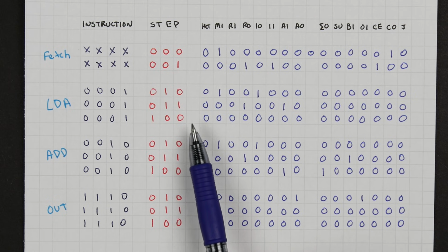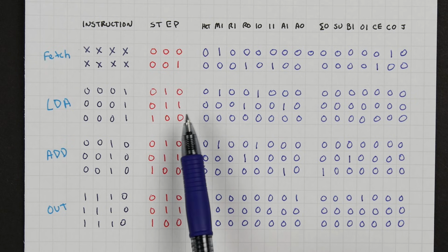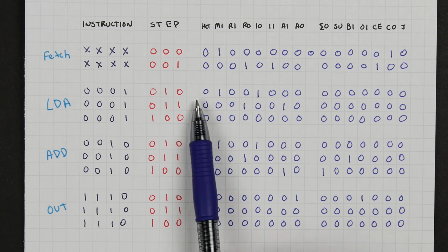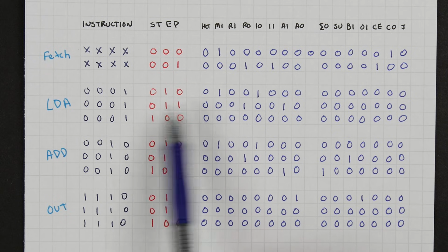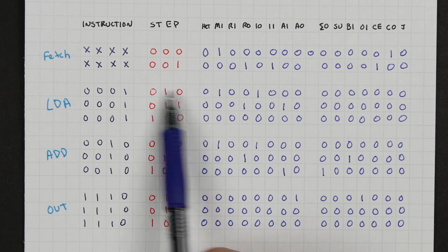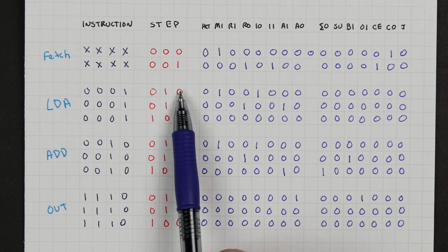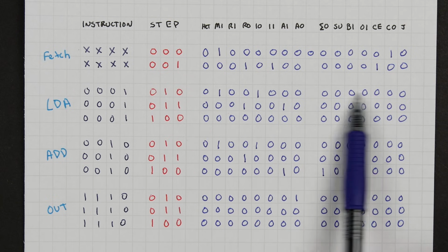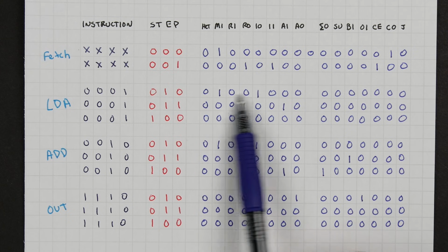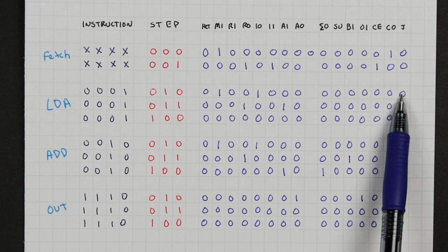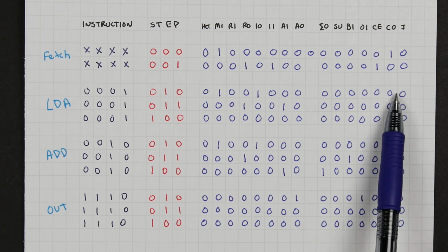But you may also remember that we were able to simplify that by using an EEPROM. And in fact, if you look at this, you might think, well, this would be very easy to do with an EEPROM because you've got these 7 bits over here that are inputs, and you can imagine those being the address into a location in the EEPROM. And then these 15 bits over here, you can imagine being the contents that are stored in the EEPROM. And that's exactly what we're going to do with this computer.